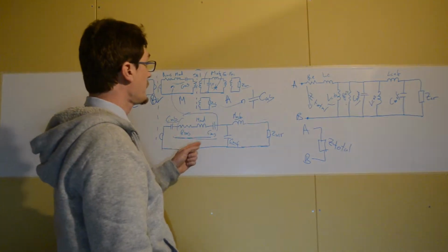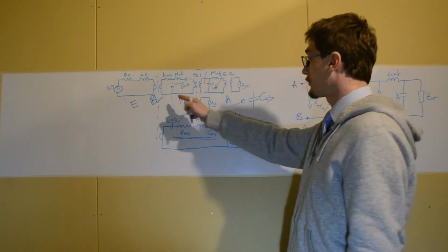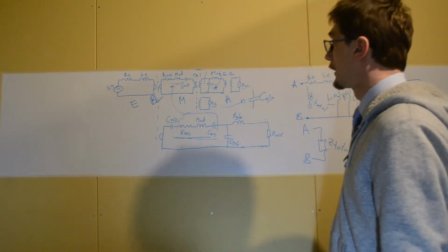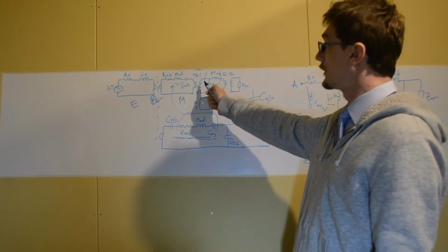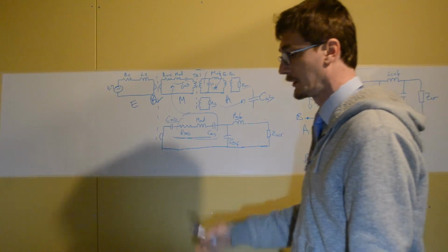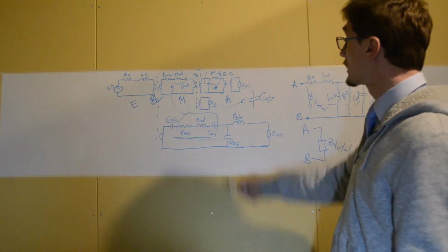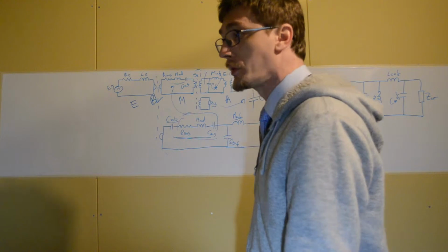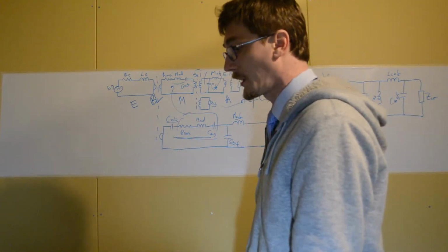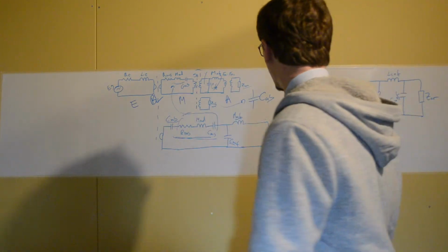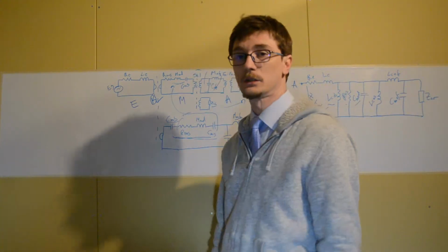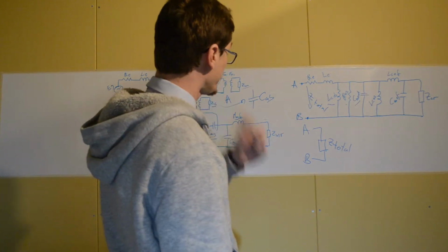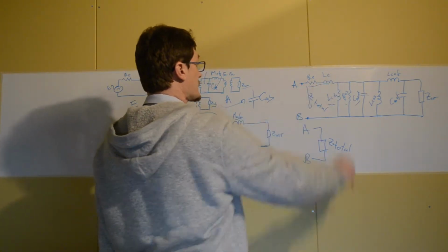Now, when we move it on the electrical side, we don't have a transformer here, we have a gyrator, so the transformation will be a little bit more complicated, because series elements will become parallel on the electrical side, and parallel elements will become series elements, and the reactive components switch their character once going through the gyrator. So an inductance will become a capacitance, and a capacitance will become an inductance. I've already done it here. Of course, the electrical ones will remain the same.